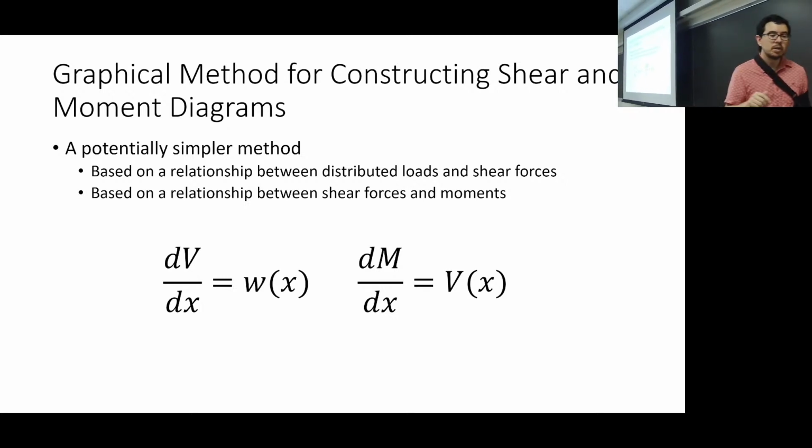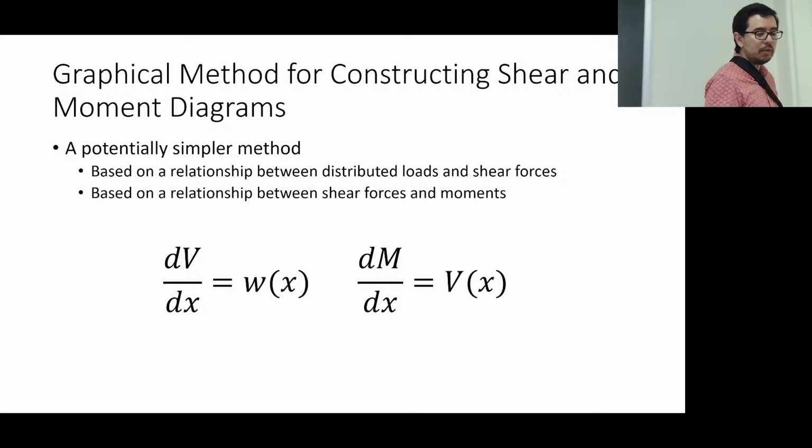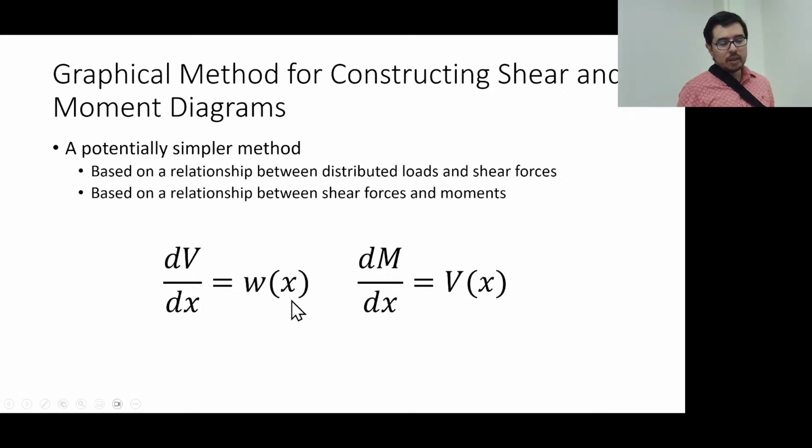What does that mean? That means, for example, if I have the distributed force, I can integrate it. I could do w(x) dx equals dV. If I integrate both sides, then I've got V equal to the integral of w(x). Similarly, if I have the shear force, I can integrate that, and then I can get the bending moments.